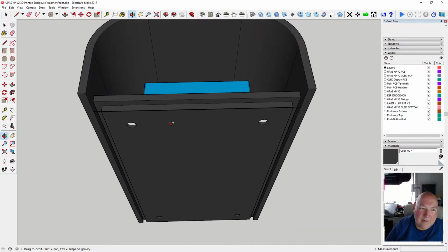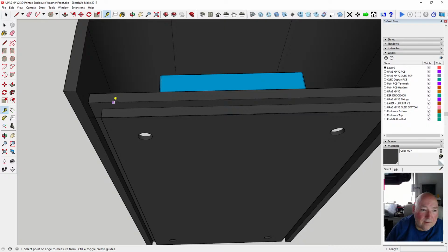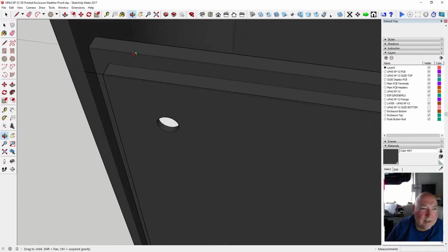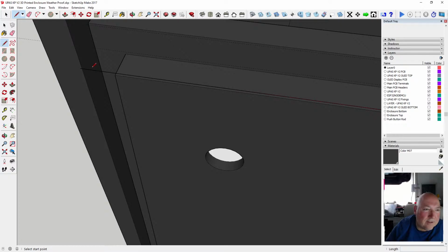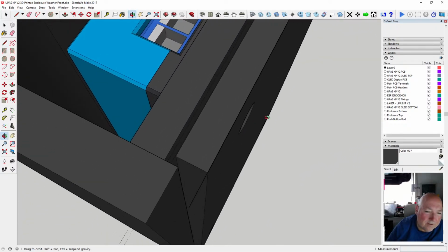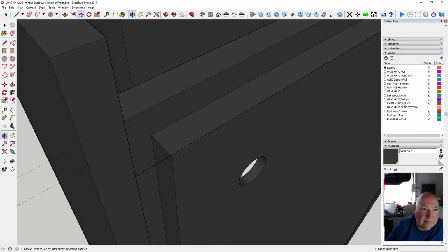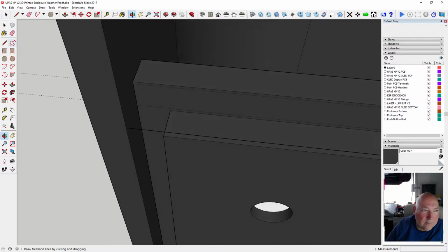Right, so we need to bring that up. It needs to have some clearance this way. So it needs to have a 0.25 clearance. So we've got our 0.25 clearance to there. We need 0.25 there. It can also be joined up with the side. Why is that? Oh, I brought it forward. Have I brought it forward? Oh, yeah, I know what I did. So we've got to bring that one over in 0.25 to line it up. Yeah, and now we can draw the bottom and the side.